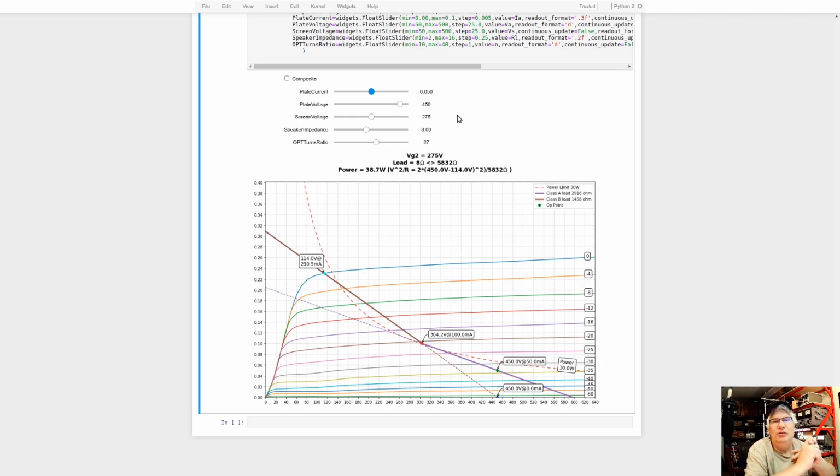You have a power transformer, and you're going to decide between tube rectification or diode rectification, and then the applied voltage drop there. So that, and the filtering, if you have a resistor in there or capacitors or whatever, the power supply is going to put out a voltage, and that is going to set the plate voltage for your design.